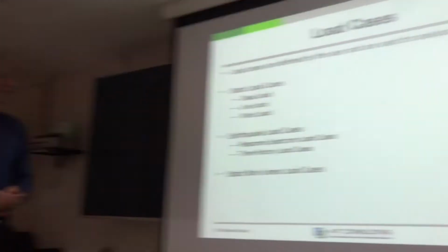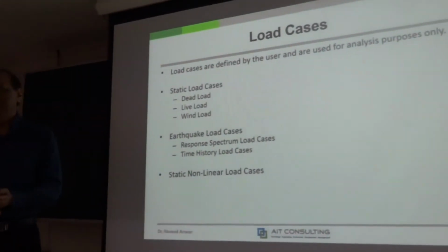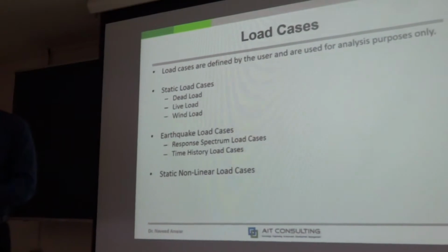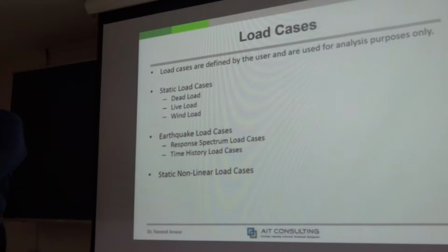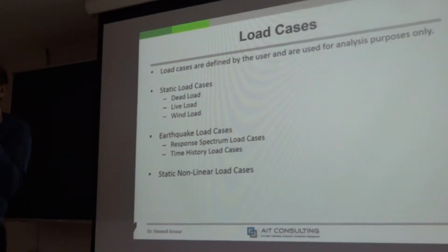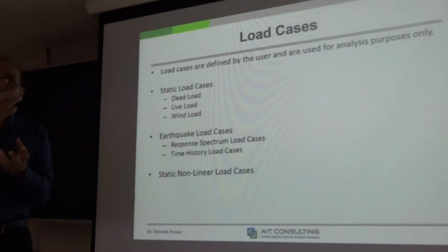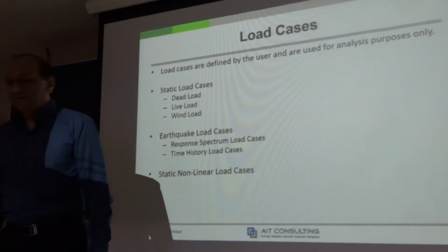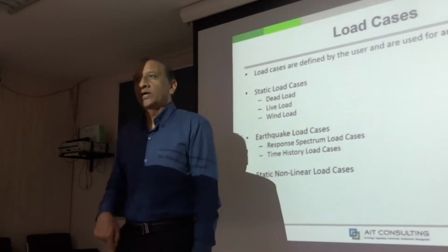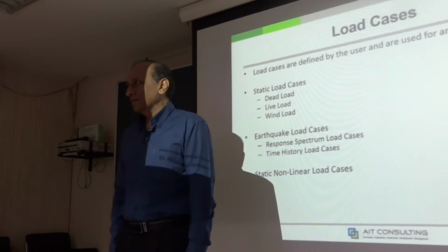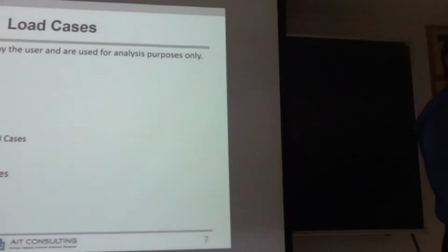Load cases. Load cases are defined by the user and are used for analysis purposes only. They are not used for design, only used for analysis. That means to find out the response for a particular load. Why do we call it load case? That means a particular loading location. For example, if I'm standing here, then I can calculate the bending moment for this slab with one point load, which is me, one load case. If I move here, another load case. If I move here, another load case.